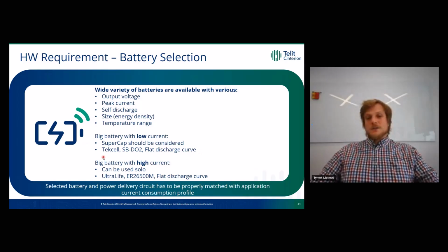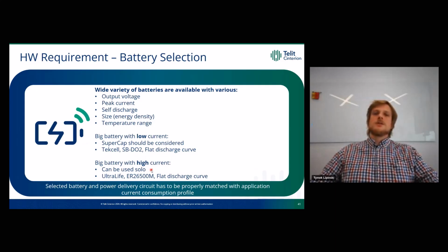Another selection, we can go with a very big battery with high current capability. So it can be used solo. We don't need any external support circuits like DC to DC converter or supercap. One from Ultralife is very nice. It has a flat discharge curve, but the drawback is cost. It's really, really costly.